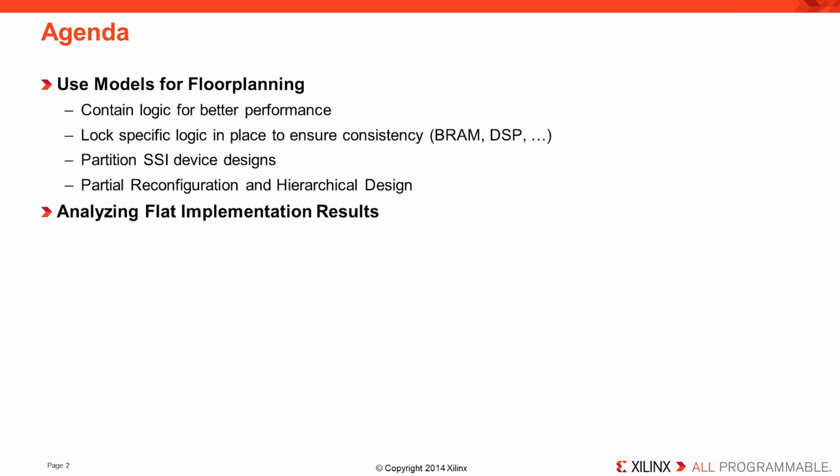We're going to start off the demonstration today by analyzing some flat implementation results that do not meet timing. We'll show you how you can use some of the design analysis techniques and features in Vivado to identify potential areas for floor planning. We'll show you how creating a dummy floor plan can help you analyze the data flow through the design, along with the resource requirements for the various logic modules.